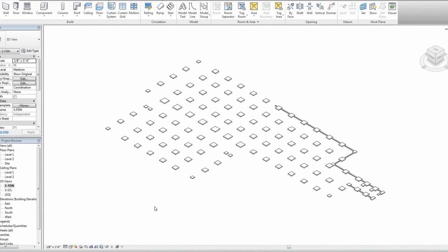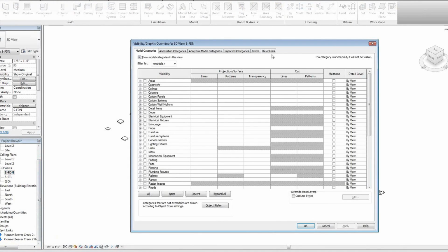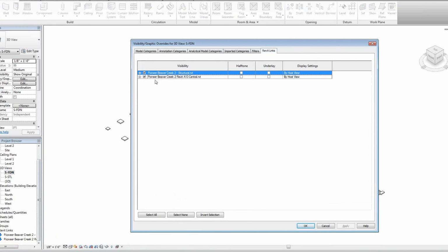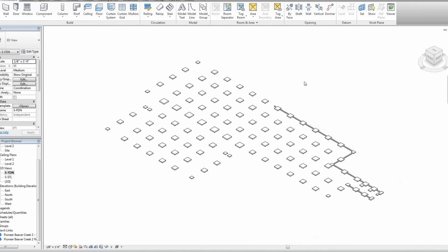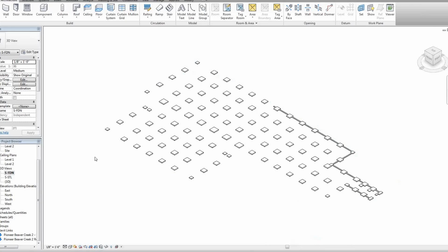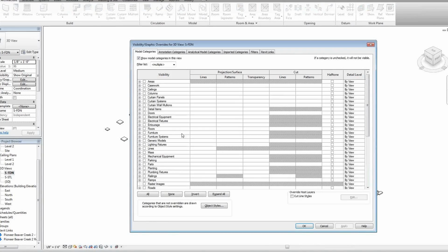Another thing to check, if you recall, we've got both the architect and the structural engineer's Revit files in here. So a lot of the time, since we're doing structural foundations, you might want to just turn off the architect's, just in case there's some miscellaneous duplicate geometry that the architect had. We were only looking at the structural engineer's model, and only at structural foundations.